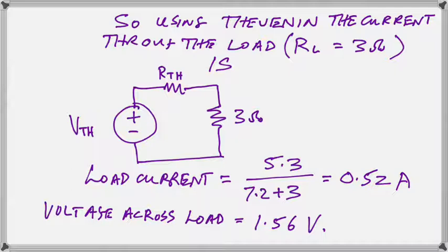Now, the rest of the problem is to prove this method. Prove this method gave us an accurate RTH. That's what I need to do, because for people who do not know the method of exciting a dead network with a voltage so that we may find the resistance of the dead network, they are going to need proof.